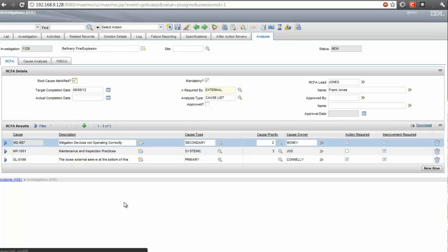They were smaller than the pipe stand, so you couldn't really see them there. So they did have a policy in place to inspect all pipe stands at a certain frequency, and they never saw any issues. Well, the problem was they couldn't see these sleeves, and of course water had collected under there over the last 40 years, and eventually caused enough rust to tear that pipe open.